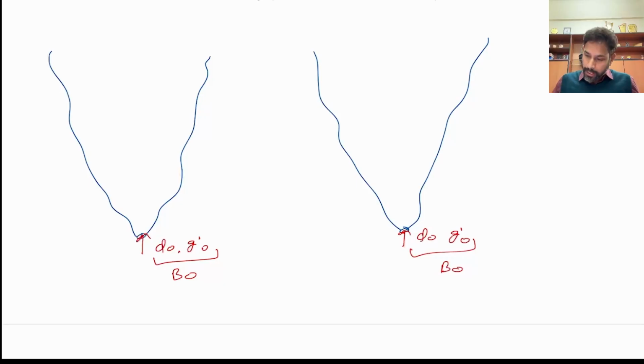When a plume comes in, obviously there is some velocity, and even if there is only a very small initial velocity, the buoyancy difference, the density difference, creates velocity, and the higher the density difference, the higher the velocity, right?